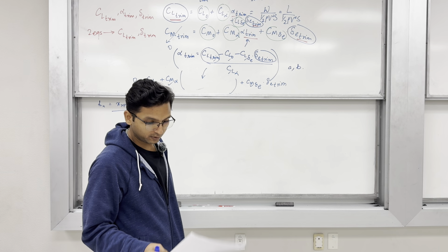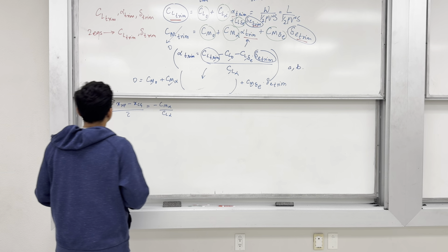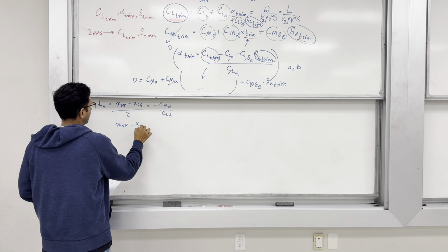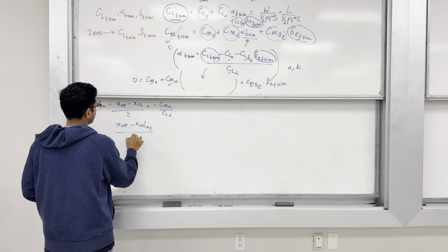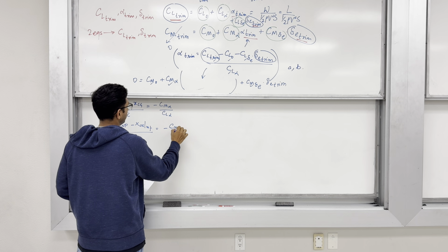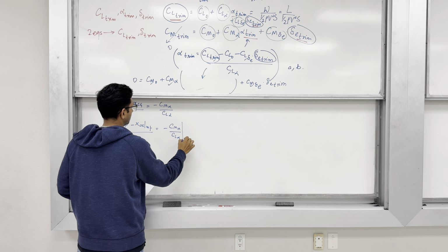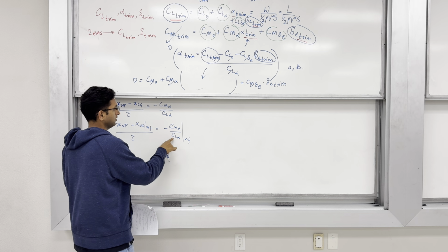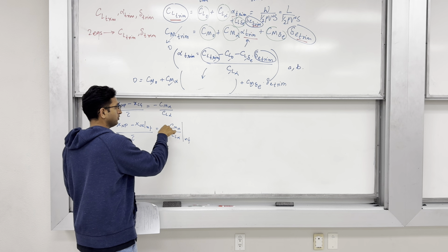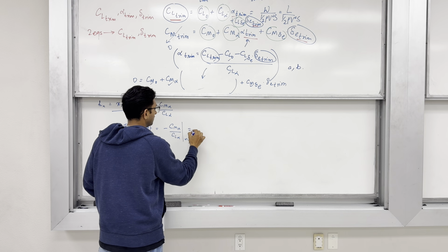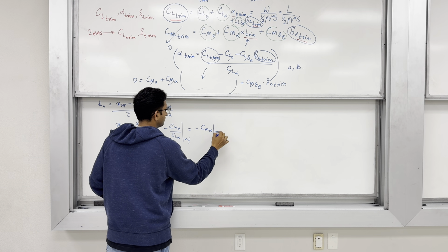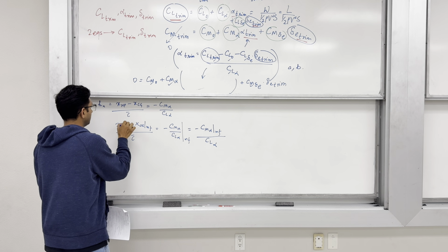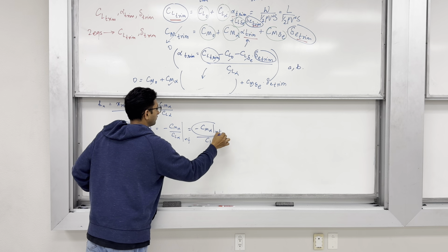But if you wanted to find out the most forward CG limit, we would have to write down an alternate form of this equation, where x CG most forward divided by C bar equals negative CM alpha by CL alpha most forward. But I know that CL alpha is not dependent on the location, it is a force coefficient. This is a moment coefficient, this is dependent upon the point about which I am taking the moment. So, I know that CM alpha most forward is not given to me, but CL alpha is the same. So, the unknowns here are x neutral point and CM alpha most forward.